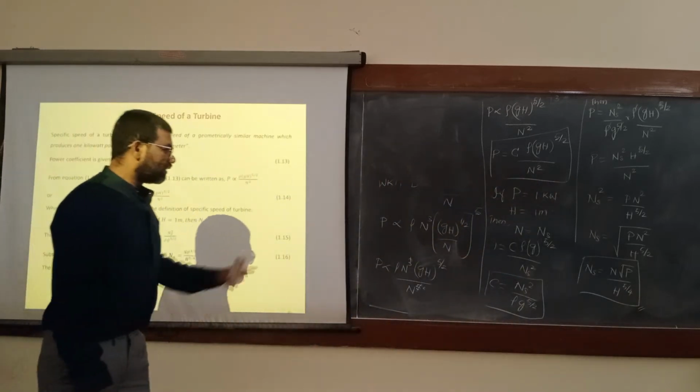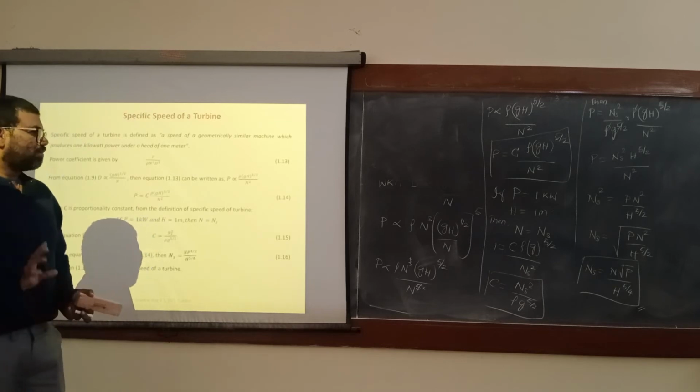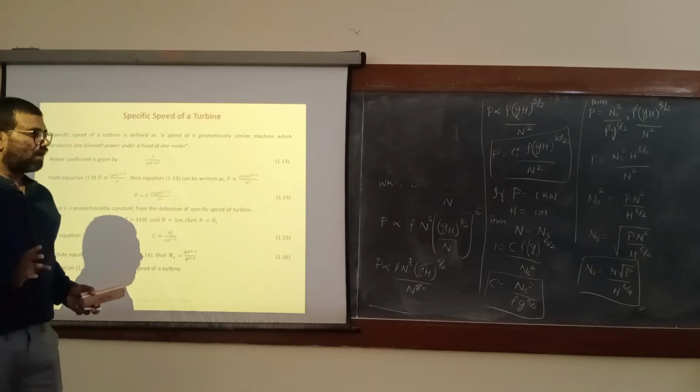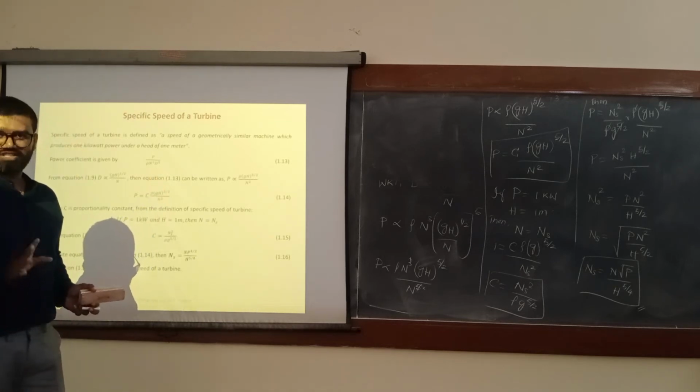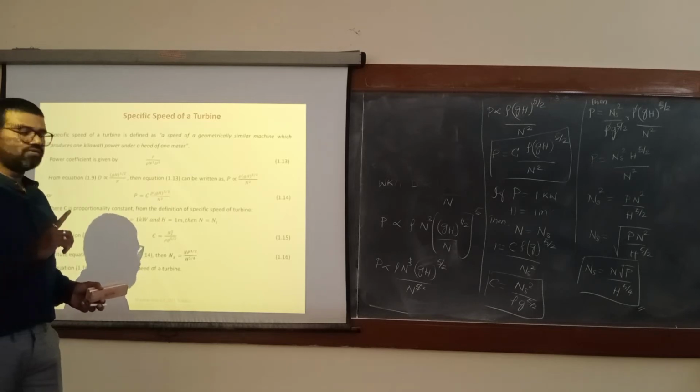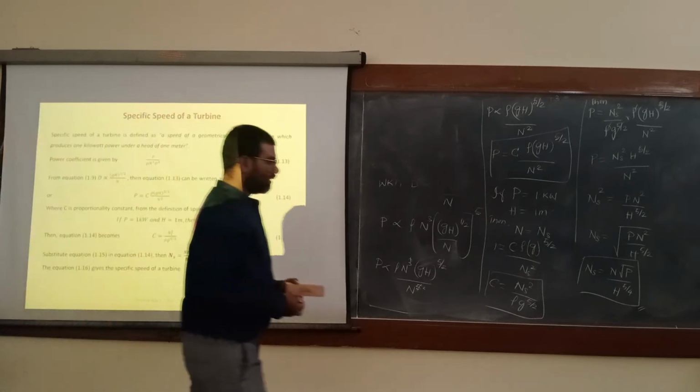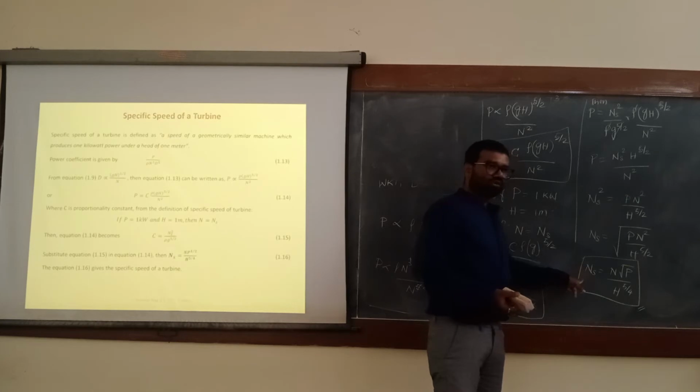One thing you should keep in mind while calculating the specific speed for a pump and for a turbine is which units are used to derive these expressions.